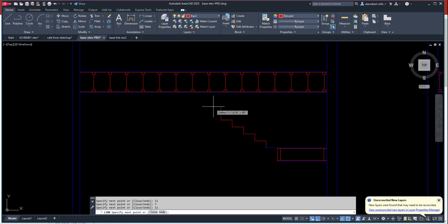And in reality, it's not really 7. It probably is 6 3/4. I'm just doing 7 right now. It's faster to do than 6 3/4. And this is just one way of doing it. You can do one step at 6 3/4 and then just copy it as you go along. Up to 7, and then go 11, 7, and do an 11, 7, and do an 11. And I'll just show you how to do the other one later.